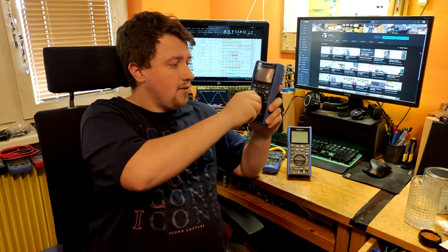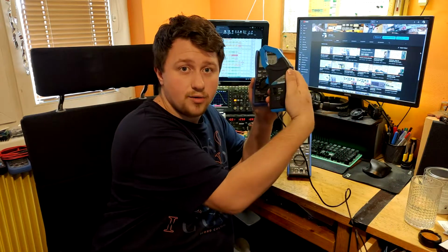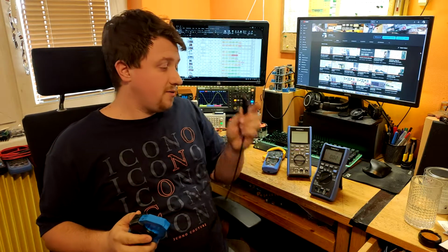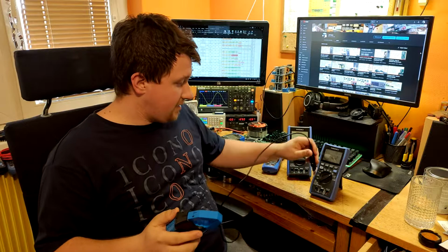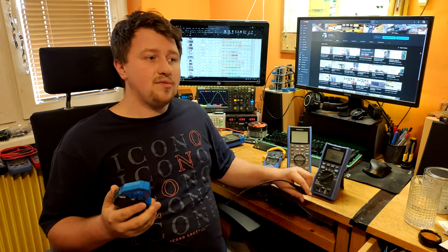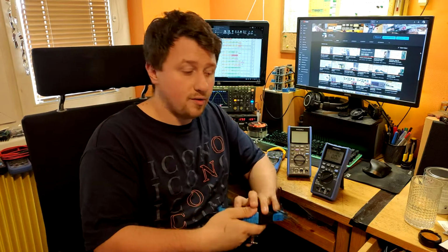Hioki can measure THD for both voltage and for current. You can also use a current clamp. I have this Hantek one here, so you can see what it looks like. They are usually with a BNC connector, or you can use an adapter for bananas. These current clamps are made by many manufacturers, and sometimes they are even compatible when it comes to signals. They usually output like 1 millivolt per 1 amp or so. Some of them are even adjustable.